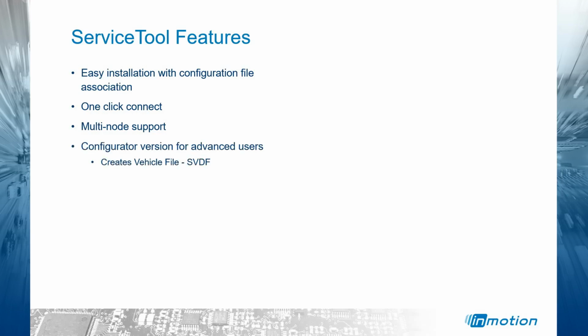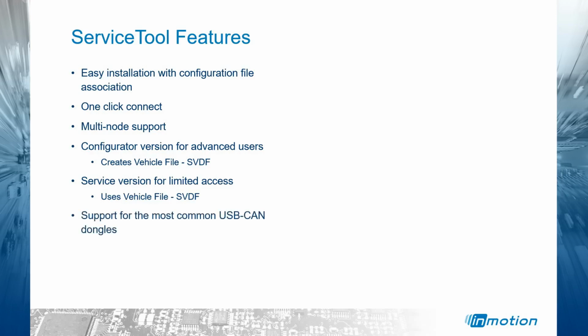We have the Configurator version for advanced users. This is the version that creates the vehicle file, the SVDF. We have the service version for limited access. This version uses the vehicle file, the SVDF. It supports the most common USB CAN dongles.